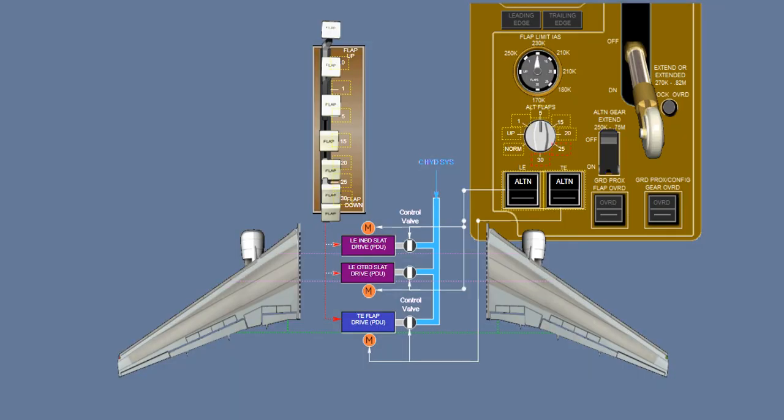According to procedures, the alternate flaps are not selected beyond 20 because flap retraction from 30 to 20 in case of a go-around would take too long. Therefore, the alternate flap positions of 25 and 30 are not used.